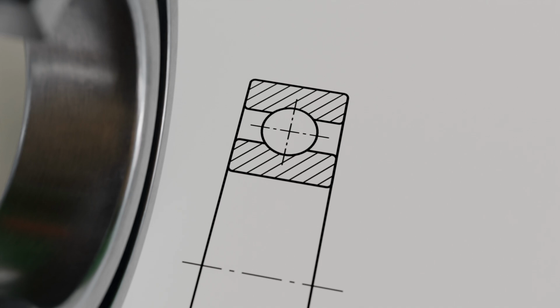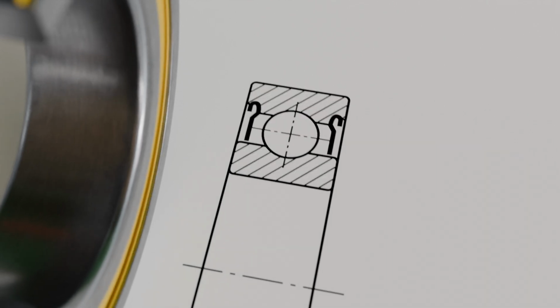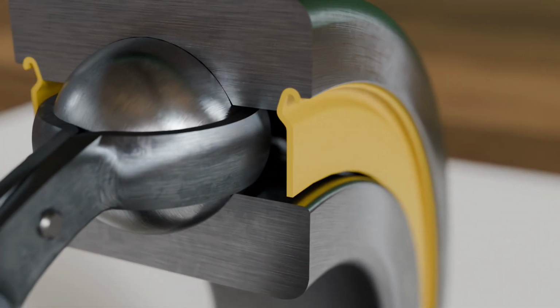Deep groove ball bearings are available both in open designs and with shields. These non-contact metal shields protect the bearing from coarse dirt and splashing water, but offer only limited protection against moisture or fine particles. Their advantage lies in very low friction. The shields are firmly mounted in the outer ring without touching the inner ring. As a result, the maximum permissible rotational speed of the bearing remains unaffected.